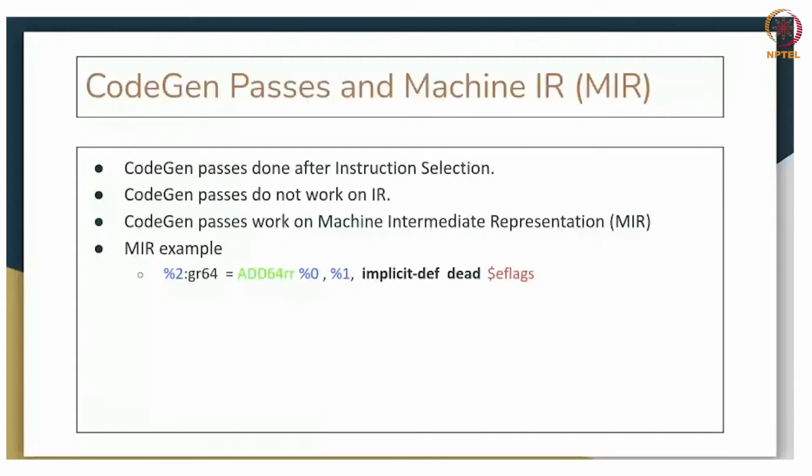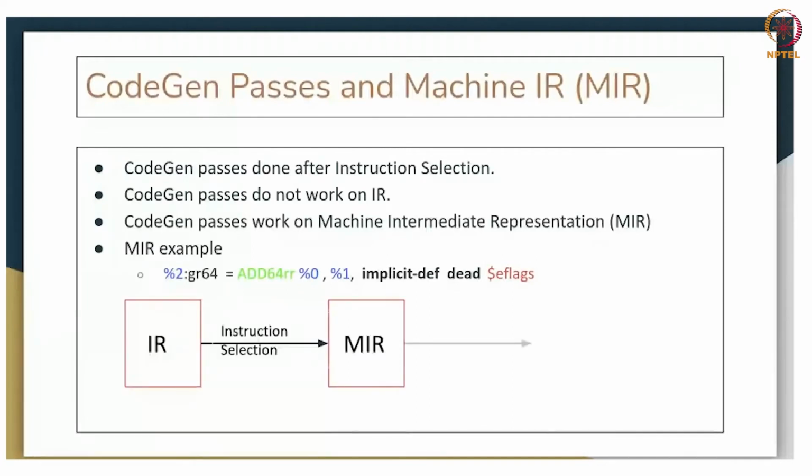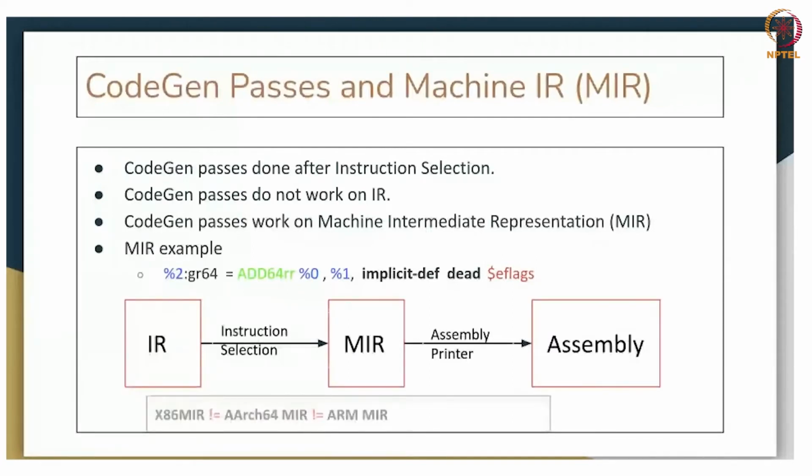What they basically said was that in x86 you have this really complex decode stage, which decodes your instruction into multiple micro-ops. They said we are not going to have this CISC style of doing things.